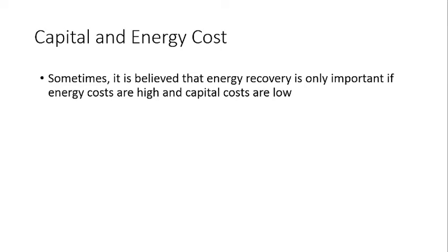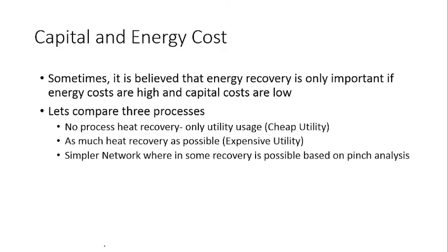So let's talk about capital and energy cost. Sometimes it is believed that energy recovery is only important if energy costs are high and capital costs are low. That means if I have a heat exchanger consuming a very high amount of energy and the capital cost associated with the heat exchanger is low, then only do I think that energy recovery is helpful. But that is not the case. What we have to concentrate on is the total cost. Total cost is made up of both components, capital cost and energy cost. If you can reduce the energy consumption, capital cost can also go down.